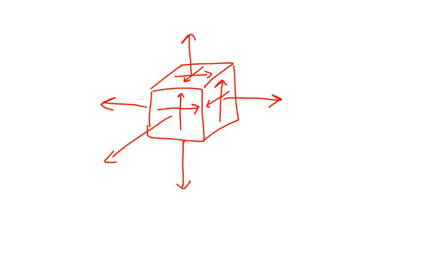Okay, so let's just bring deformations into this whole idea of a general state of stress. Okay, so this is my coordinate system. Horizontal is x, right? Vertical is y, and the axis that comes out of this page is the z-axis. Based on this coordinate system, right, these two stresses here are sigma sub x. These are the normal stresses in the x-plane, right?